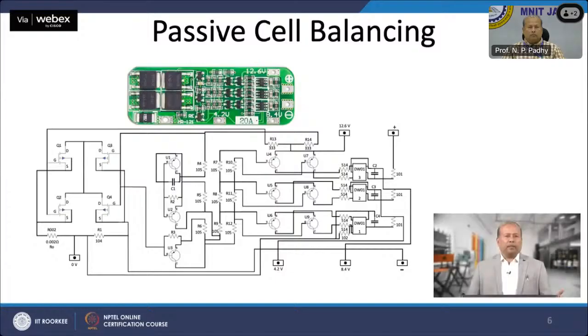This is the schematic of the balancer IC, which consists of 4 N channel 85N3L switching MOSFETs, DW01 overcharging and over discharging protection IC, G1 SMD NPN high voltage transistors, 2L PNP high voltage transistor, 1 port charging and discharging terminal and a few resistors and capacitors.